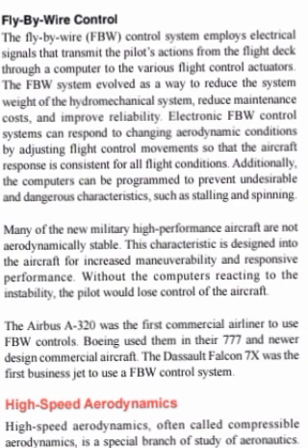Fly-by-wire control. The fly-by-wire control system employs electrical signals that transmit the pilot's actions from the flight deck through a computer to the various flight control actuators. The fly-by-wire system evolved as a way to reduce the system weight of the hydromechanical system, reduce maintenance costs, and improve reliability.